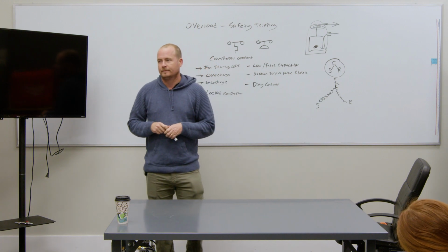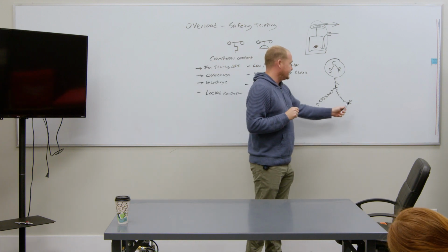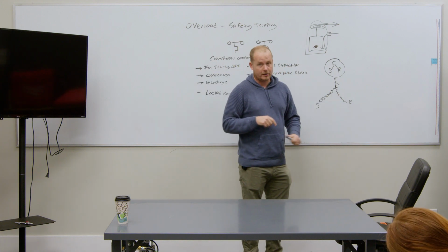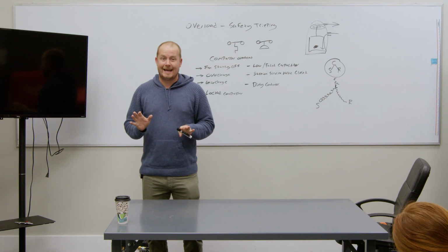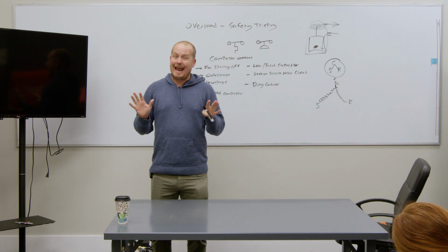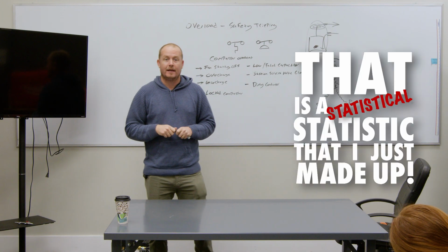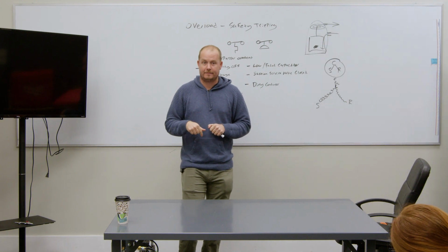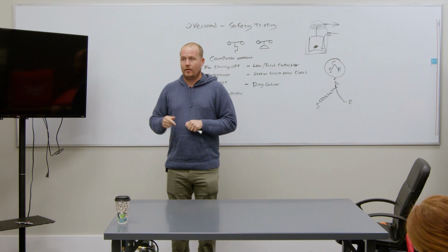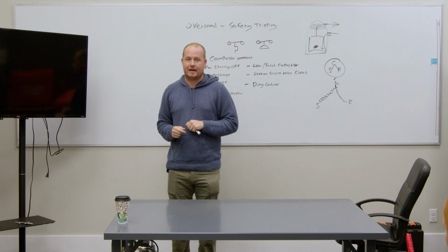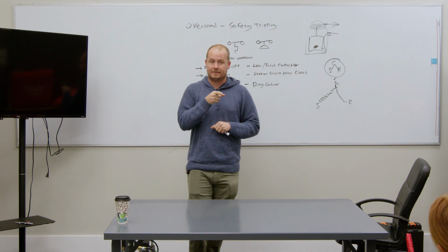No. Let's see if it works now. No. But when you're measuring ohms between start and run, but not between run and common or start and common, you have an open thermal overload. And I would say 98% of the time, that is a statistic that I just made up, 98% of the time it will reset. Are there cases where it just decided not to reset? Sure. But guess how the compressor will feel if that's the case?